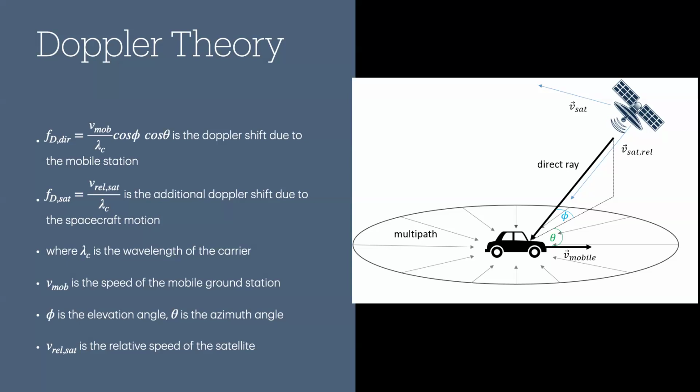The frequency appears to alter as we receive it, and the spacecraft appears to have a different frequency because of its movement. When it comes over the horizon at us, it's moving towards us at a considerable speed, and depending on the frequency that you're transmitting to it and the frequency that it's transmitting, that variation could be as much as 11 kilohertz in the bands that we're on. That takes you out of channel, out of band. That means you can't hear the signal anymore. So you have to compensate for it. And this is called the Doppler shift, and it's one of the most important parts of spacecraft communication.